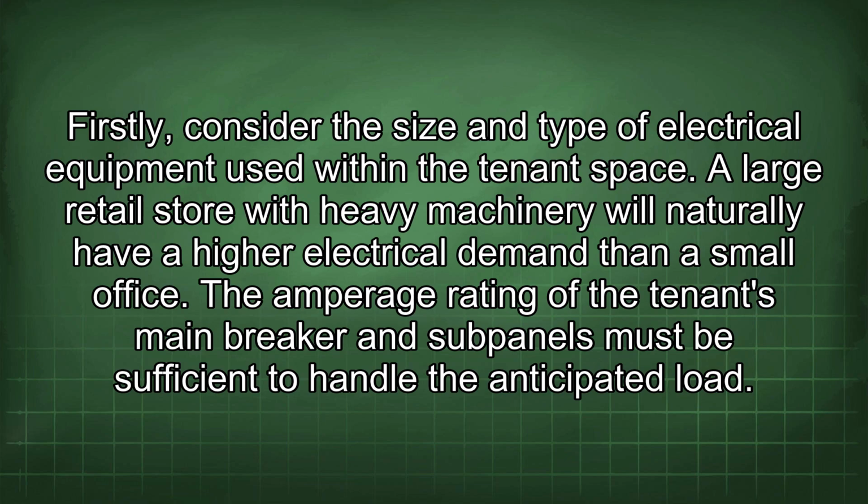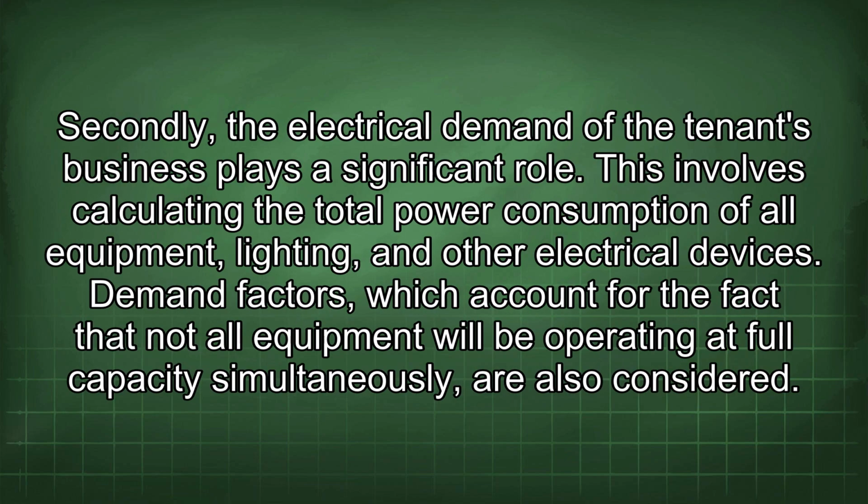A large retail store with heavy machinery will naturally have a higher electrical demand than a small office. The amperage rating of the tenant's main breaker and subpanels must be sufficient to handle the anticipated load. Secondly, the electrical demand of the tenant's business plays a significant role. This involves calculating the total power consumption of all equipment, lighting, and other electrical devices. Demand factors, which account for the fact that not all equipment will be operating at full capacity simultaneously, are also